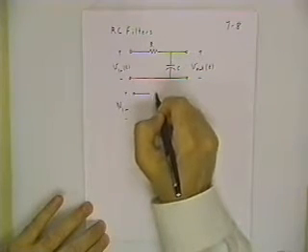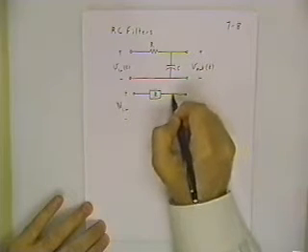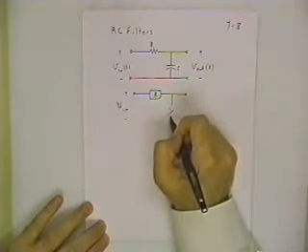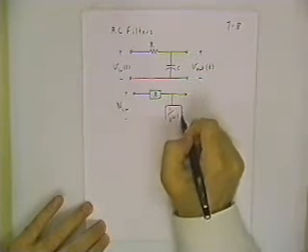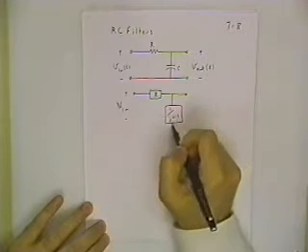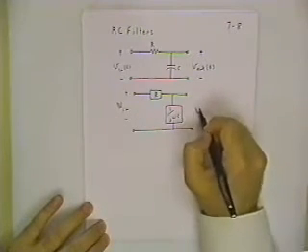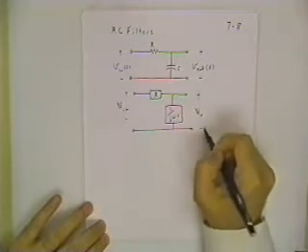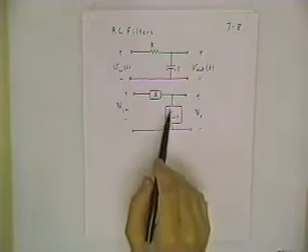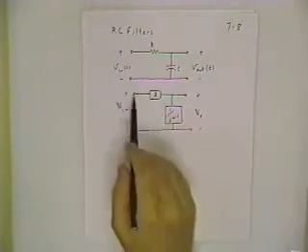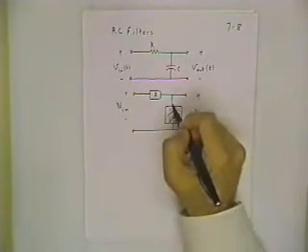I have an impedance R and an impedance for the capacitor. Let me express that as 1 over j omega C. And now we have an output voltage. Well, if it's true that I can handle this circuit with impedances the same way as I handled a similar DC circuit with resistances, I should be able to apply a voltage divider.